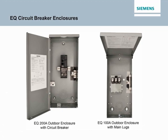EQ circuit breaker enclosures for 1-phase 3-wire 120/240 volt applications are available with ampere ratings from 60 to 225 amps. EQ circuit breaker enclosures for 3-phase 3-wire 240 volt and 3-phase 4-wire 120/208 and 120/240 and 240 volt applications are available with 100 or 225 amp ratings.